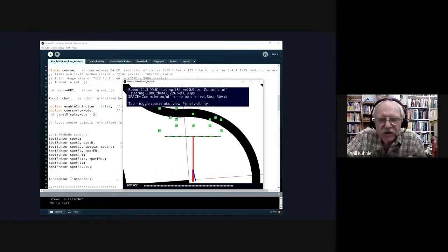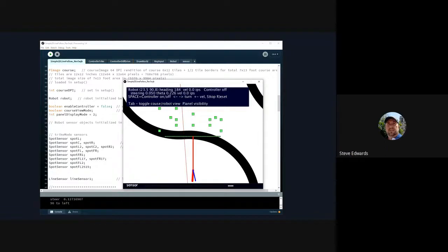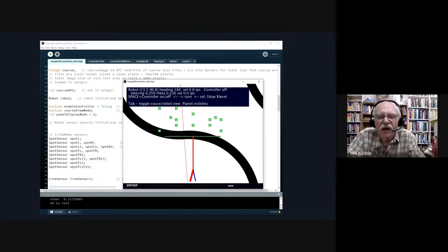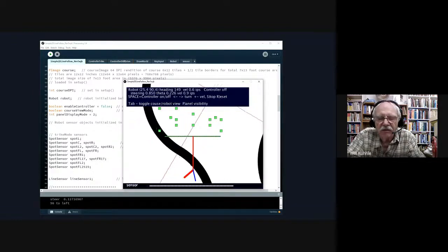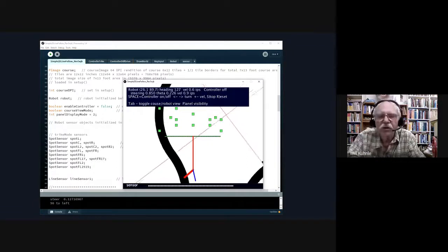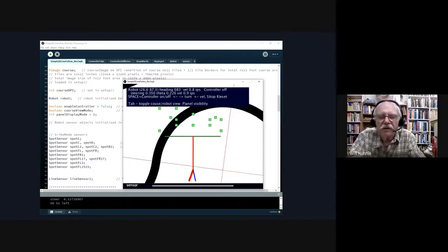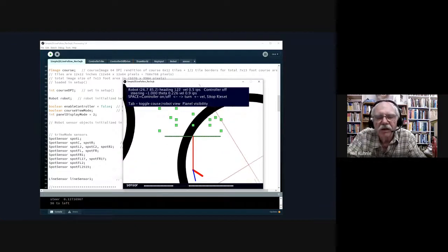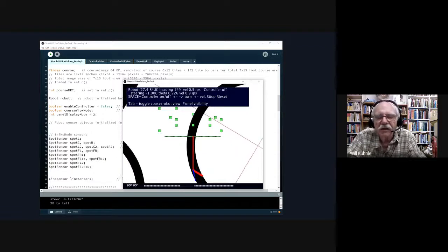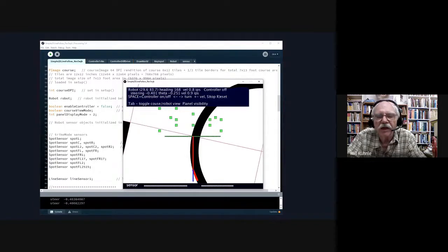One of the problems I run into is that the line sensor is quantized, so the output of the line sensor is not a continuous smooth curve, it's a staircase. When you differentiate a staircase by taking the difference between the current and the past reading, you get a bunch of spikes more than anything else.